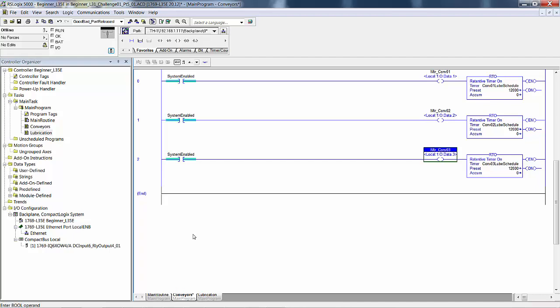There are 2 methods to determine full: by counting cartons onto and off of each conveyor and specifying a full preset for the counter, or when a carton arrives at the interface between 2 conveyors and the photo eye to the next conveyor senses its presence and determines that the previous conveyor is full. You can do it with counters or you can do it with photo eyes.